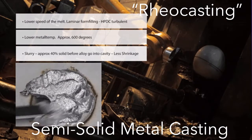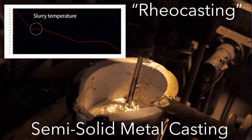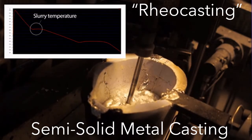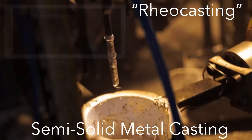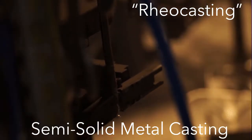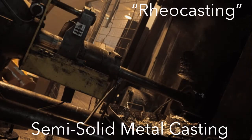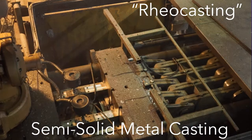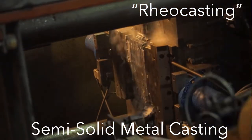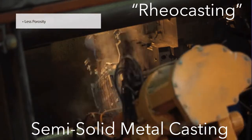To flow properly, the mixture must consist of solid metal globules in the liquid. To achieve that, the mixture is stirred to prevent dendrite formation. The mixture is then applied to a piston that injects it inside the mold. Leave it to solidify, cool down, and eject it.